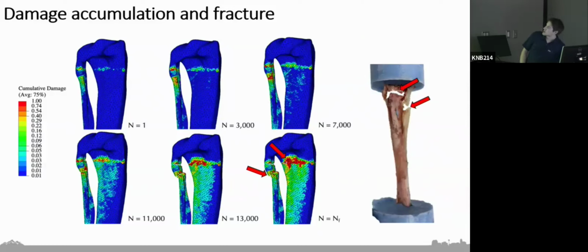Yep, it's a really good question. So we're only loading uniaxially. And what we would see a huge effect from with the isotropic or anisotropic material properties of bone is when we load in torsion. I do expect that if we were to apply torsional loads to this model, we would underpredict strain in the torsional direction, because we model this isotropically. But you're right, that introduces some level of error. It's not necessarily completely valid. But because we're loading uniaxially, there are very limited effects from the anisotropy of bone when we're loading in that one direction.